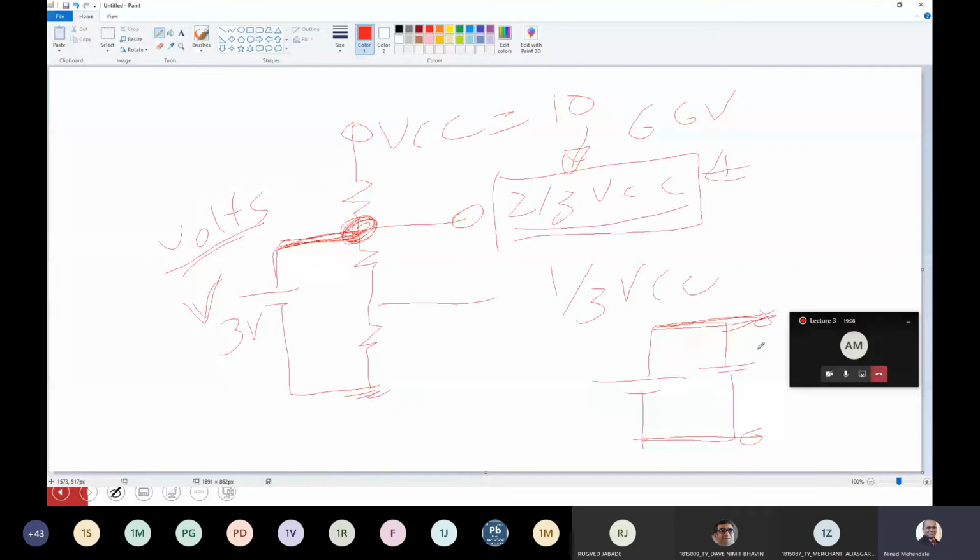But I guess in the first lecture, I have already told you, when you connect 2 supplies with the same polarity, the output voltage is always the lower voltage. Reason being, loading will happen and the higher voltage supply gives current to this battery, and this becomes dangerous because the battery is not prepared to accept any current.